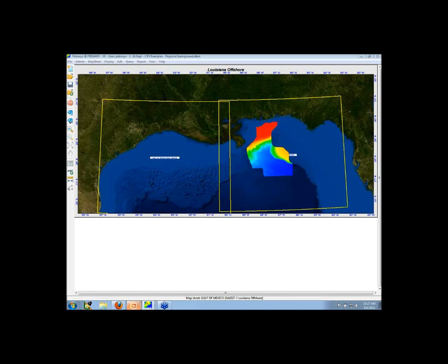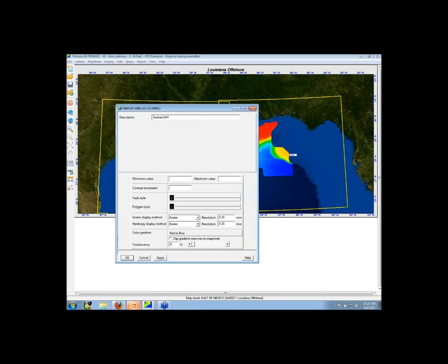And one of the nice things about Petrosys is if there's what we call metadata, so if your data has some sort of CRS information tied to it, Petrosys will read that and end up displaying everything in the correct place because we run on-the-fly transformations of data, and that's using multiple transformations. In this case, let me take a peek here. If I pop open some of the details of this grid, we can see that there's this NAD 27 UTM zone 16 north.